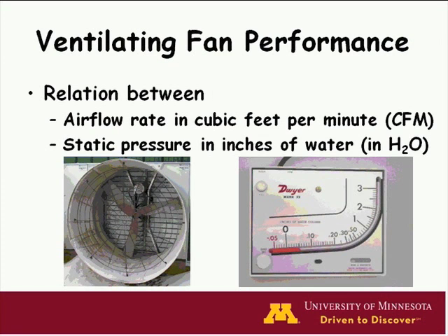Finally, I want to talk about this concept of agricultural ventilating fan performance. This is the key part of working with a ventilating system. The fans are the heart of the system, and to help us understand their performance, we need to know the relation between the airflow rate and the static pressure that the fans are working against while providing that airflow. So static pressure indicates what the fan must overcome or work against while providing this airflow.